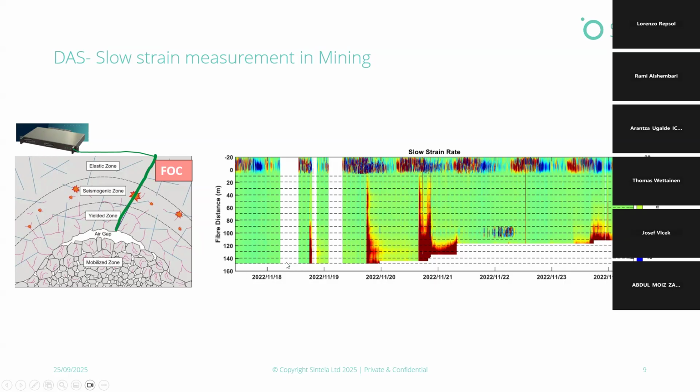So as time goes by, every time there is that fracture propagation building up, you can see early signs of it on the strain response of fiber optics. And before that fracture propagates and breaks and the rock mass breaks and the fiber breaks with it, we see that increased response in slow strain. And then the fiber gets cut, and then we continue to monitor the remaining fiber for that slow